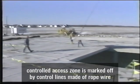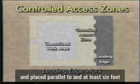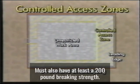A controlled access zone is marked off by control lines made of rope, wire, or tape supported by posts and placed parallel to and at least 6 feet but not over 25 feet from the leading edge. In overhand bricklaying areas, the lines must be between 10 and 15 feet from the leading edge. Control lines must also have at least a 200-pound breaking strength.